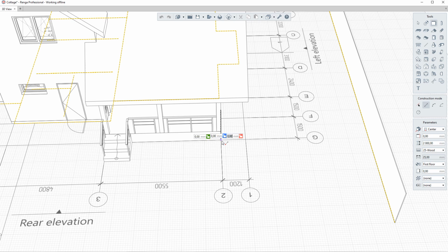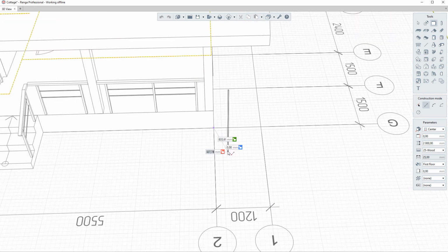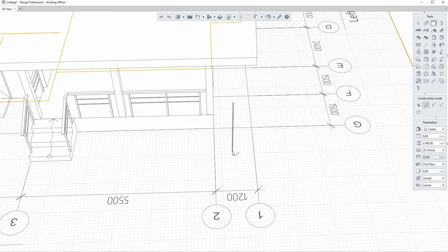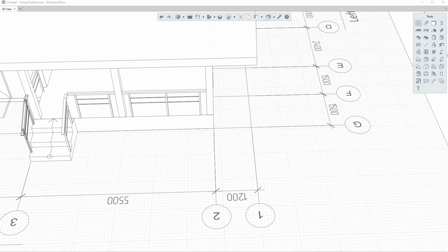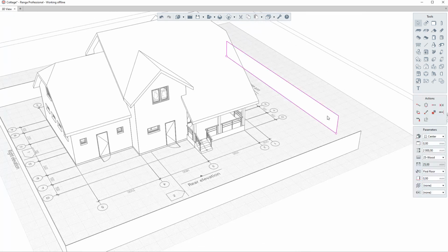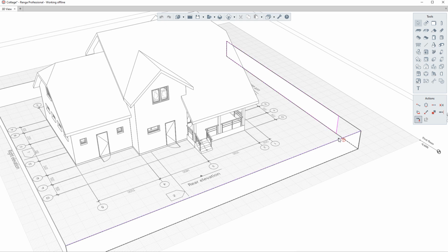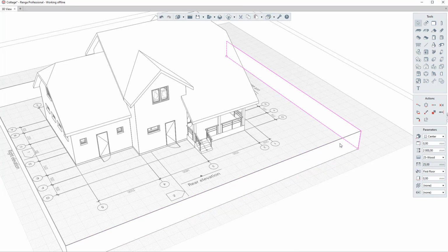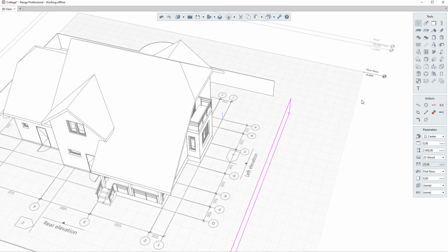If you activate a snap point and need to deactivate it without the construction being interrupted, hold the pointer onto the snap point. To complete the construction, click on the first wall and activate the command, trim or extend to corner, on the Actions panel. Specify the baseline or edge of another object. Left-click to fix the objects. Repeat the steps with the remaining wall.